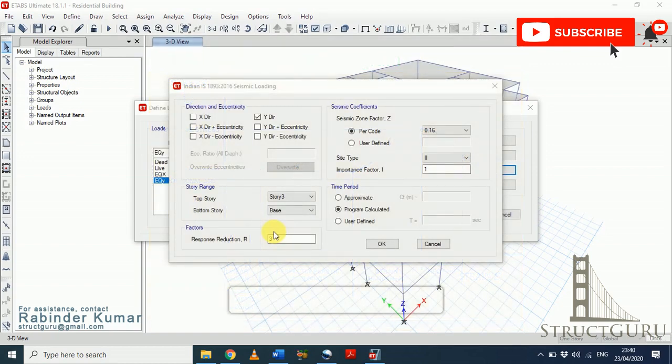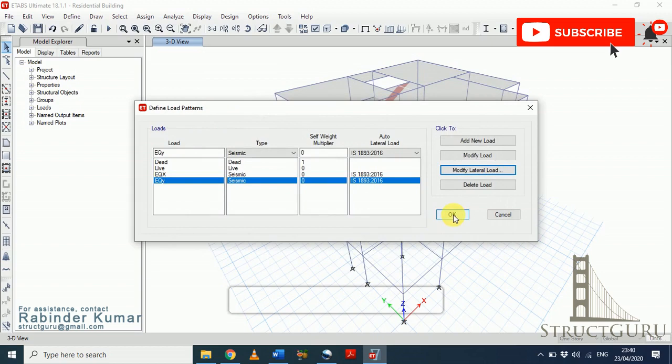Earthquake resistant structures means it can experience small cracks in the buildings, or some building components may also collapse, but overall the structure will respond well against the earthquake. Now if we say earthquake resistance, the question is how we design earthquake proof structures. To do that, just type 1 in the response reduction factor input, but we don't go for this value as it will give high reinforcement for our building, and the structure will be uneconomical. So choose the value which is recommended by the code. Click OK and OK.